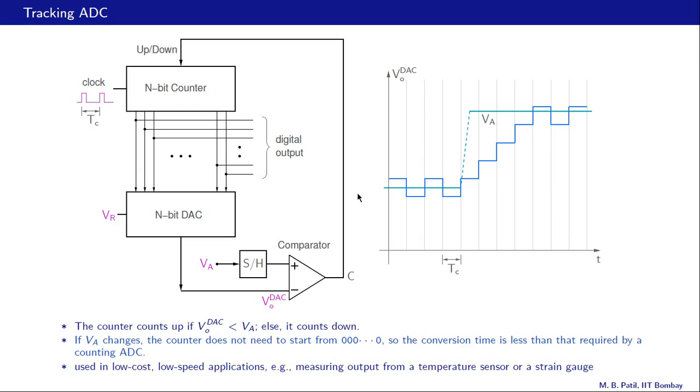These oscillations may seem like a problem, but notice that the oscillations are only in the LSB, the least significant bit of the counter. Therefore, if we have a large enough number of bits where all these other bits remain constant, then this change in the LSB may not really matter in a real application.